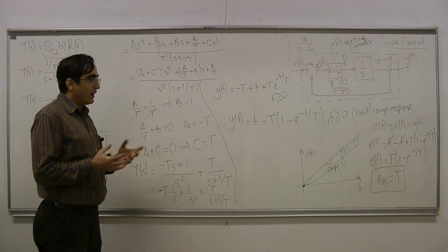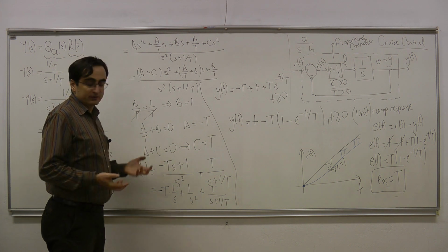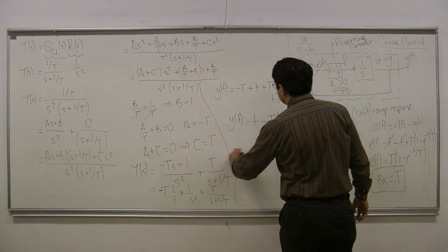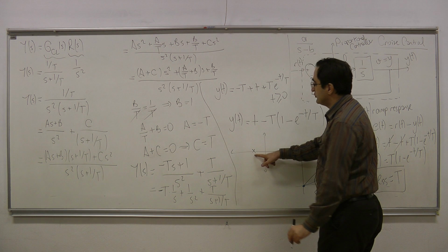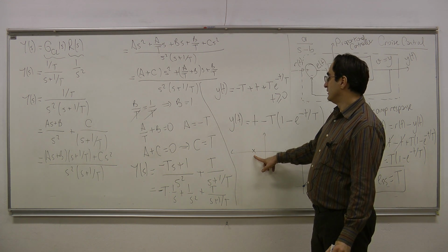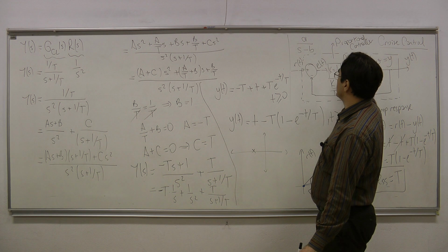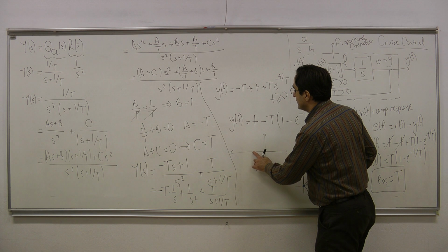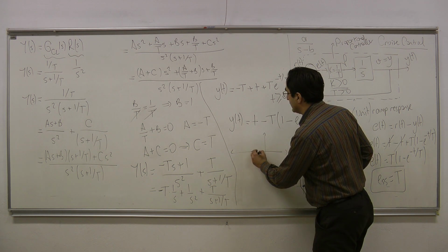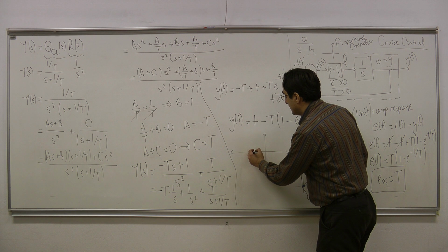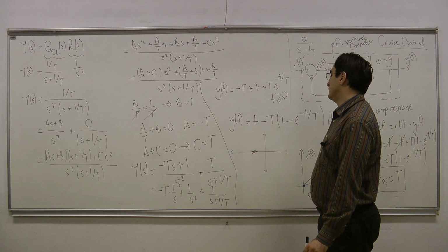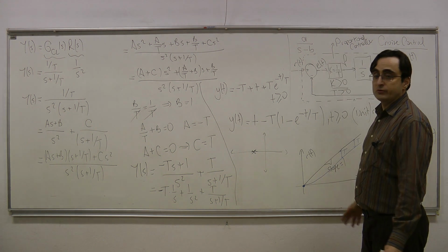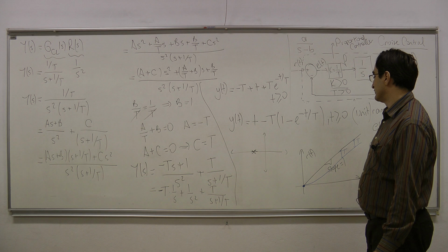And why did this happen? This happened because these first order systems would only have a single real pole. Okay? So this closed loop system had only a real pole in the open left half plane. We always had a real pole in the left half plane. And that is why we did not see any oscillations in these responses.